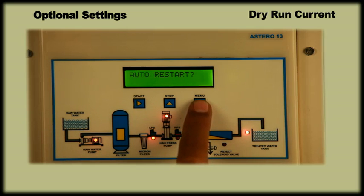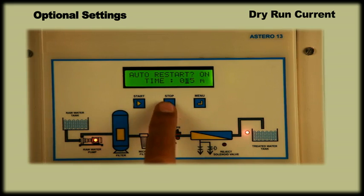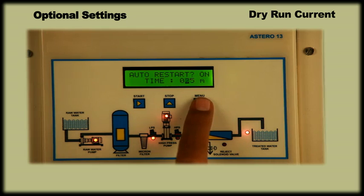By pressing Menu again, the display will show Auto Restart off. Now if you want to turn on the auto restart, use the Stop key to turn it on and press Menu. After turning it on, press the Menu key, and it will display the previously set auto restart time. That is, once the pump goes dry running, and if auto restart is on, then the motor starts automatically after the set time has elapsed. To exit, press the Menu key again.